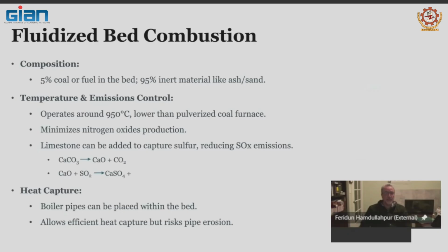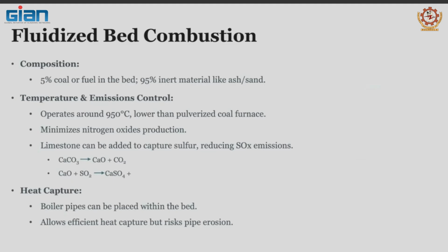So, again, when it comes to heat capture, I touched on it yesterday. Boiler pipes can be placed within the bed, with refractory preferred, but if you don't do this, you will encounter pipe erosion because of the constant impact of solid particles on the pipes.